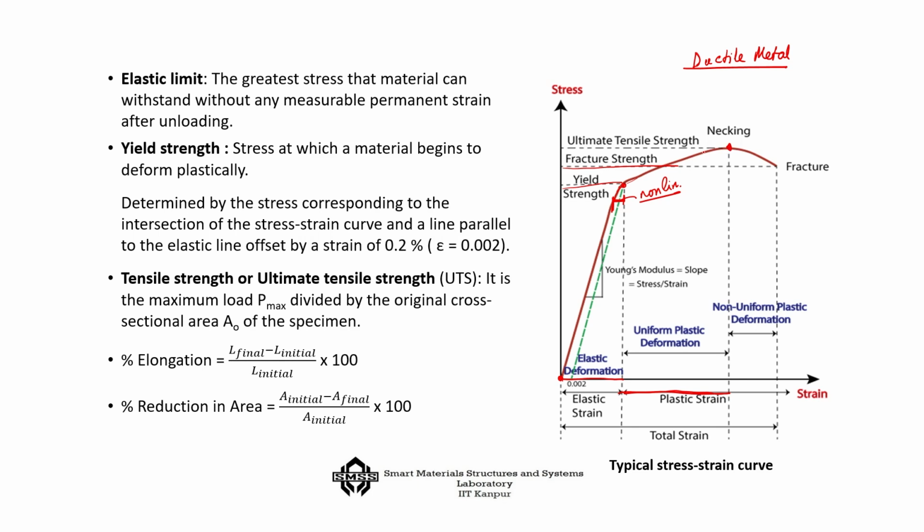Once the necking happens, in all practical sense the material is irrecoverable and the failure is going to happen. So, that is how the ultimate tensile strength is always defined, when the necking starts. Okay. So, that part beyond necking, actually the plastic deformation itself becomes non-uniform in nature.